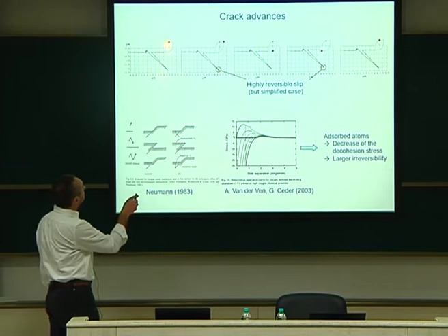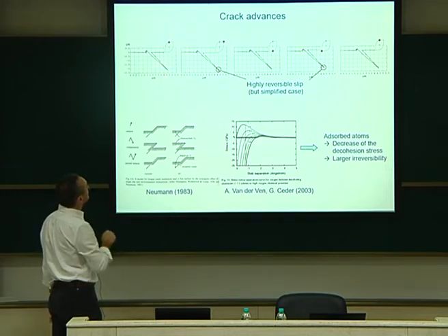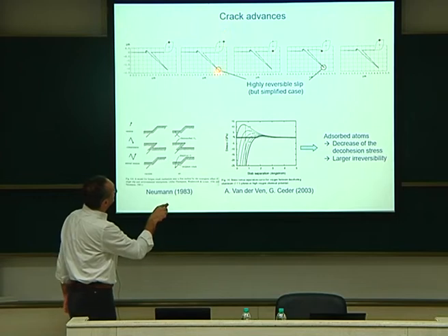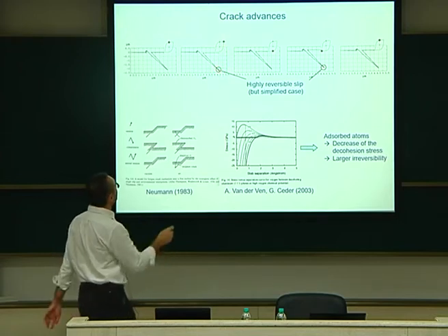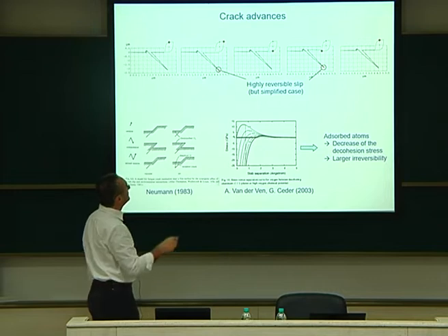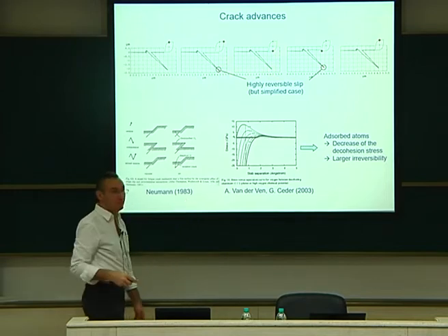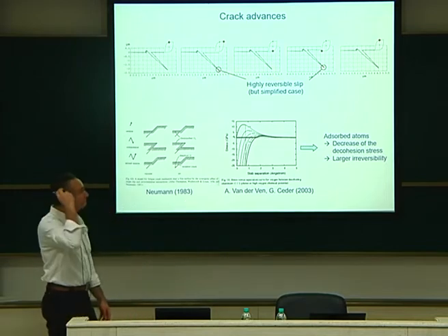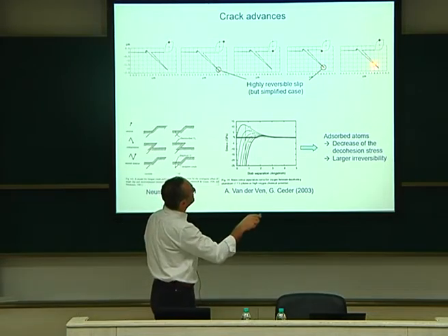So this is plotted here for different stages of a given cycle, okay? Here you have the initial position of the crack. At that stage, you can see that the crack advances a little bit. You see this is in microns, a little bit. And then when you unload, it is reversed. So a part of it, a big part of it, has been totally removed. Then you negatively load, you can see that it is shrunk, and then again it's back.